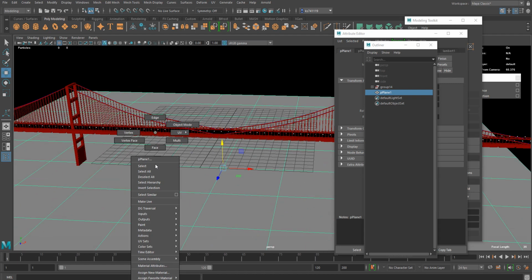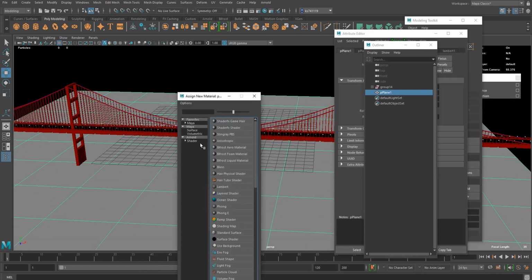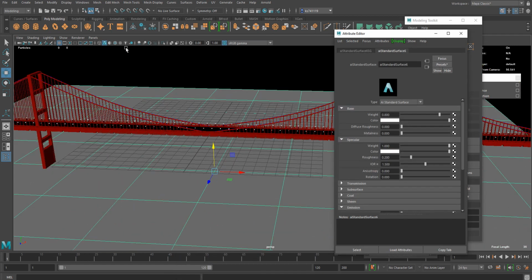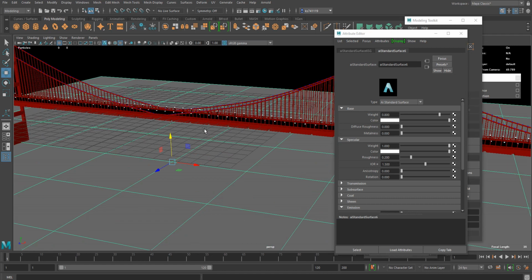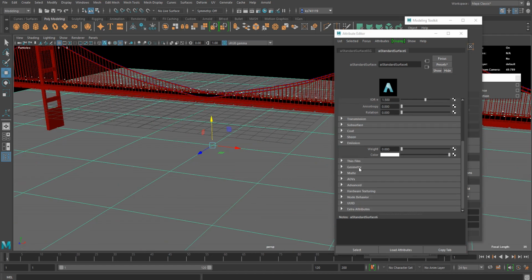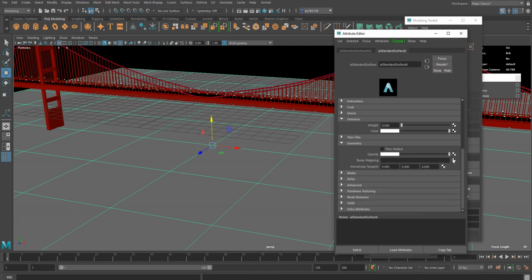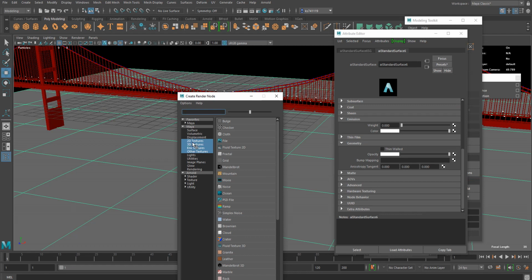Okay, now I'm just gonna apply a new material to the surface, and to make a water surface, it's a good idea to add a bump map. So you can just go down to Geometry tab and add a bump map, and you can actually work on this procedurally.